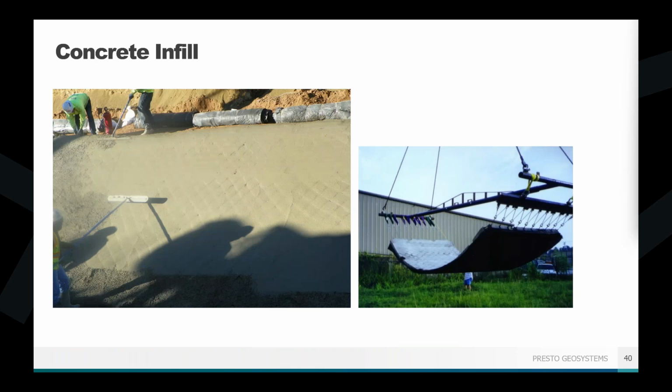And the system is actually still pretty flexible. And so we do consider it a flexible concrete mat. So if you wanted, it's not super practical, but you can actually pre-fill the concrete and then move it into place later if you want to. Typically, it's easier to put the panels directly on the slope face and then fill them in from there. But sometimes people have specific installation steps that they need to follow. And this is one of those benefits to a flexible system, that you do get a flexible concrete mat.